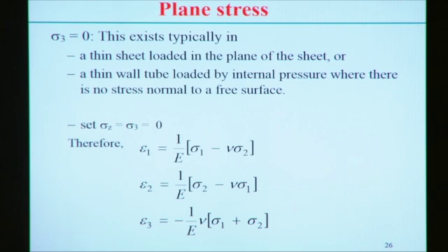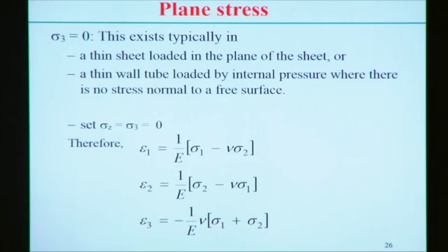Now if we look into very specific cases of the three-dimensional state of stress, one specific case is the plane stress condition. This typically exists when sigma 3 equals 0, and practically this happens in a thin sheet loaded in the plane of the sheet, or a thin-walled tube loaded by internal pressure, where there is no stress normal to the free surface.